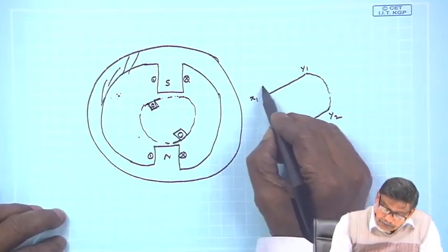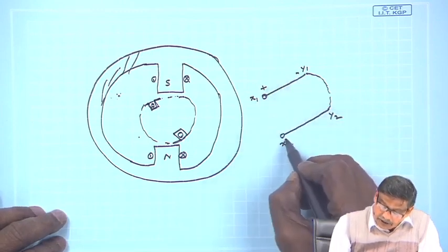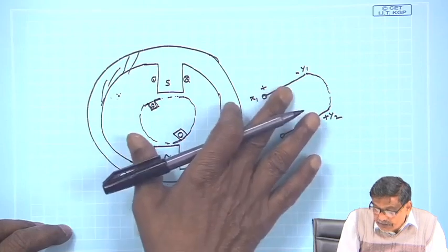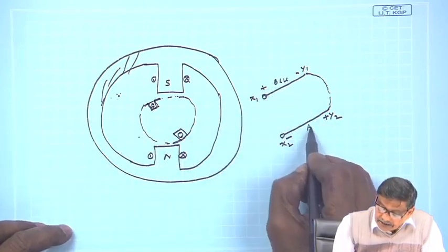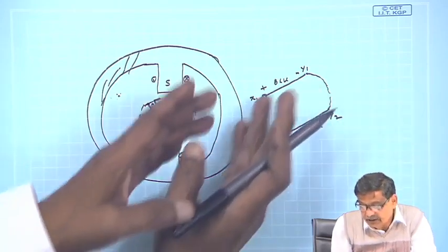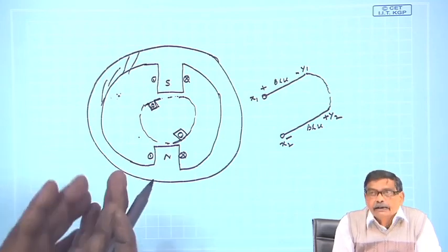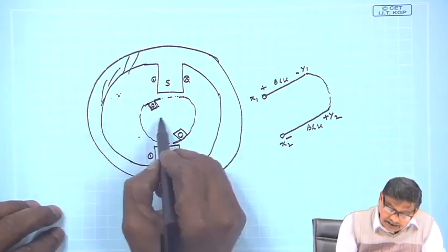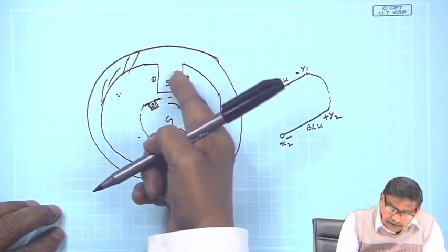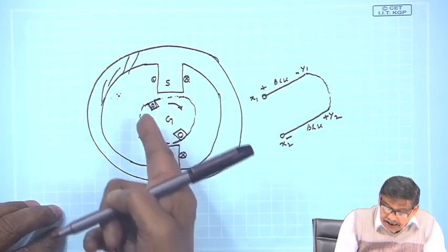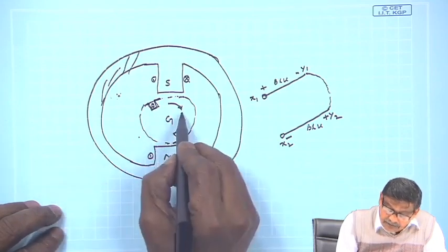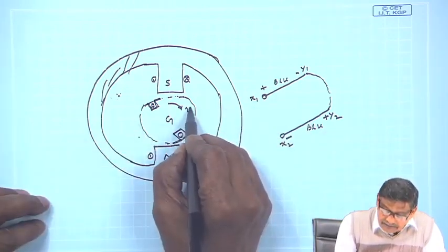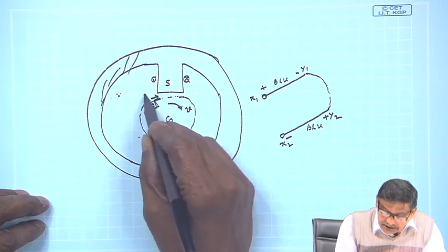And these two EMFs, if it is plus minus here, this will be minus plus there, and then the voltage across x1 x2 will be twice of these two voltages. This is vLB, this is vLB, but the polarities are such that these two EMFs get added up and you get the sum of these two voltages appearing across x1 x2 if it is operating in generating mode. Suppose in generating mode, what are the things we have to give? Create the field B, B I have created, L length of the conductors that is there, and this velocity I must provide by some external agency, say turbine or by some diesel engine, whatever it is. This will be provided by tangential velocity v.